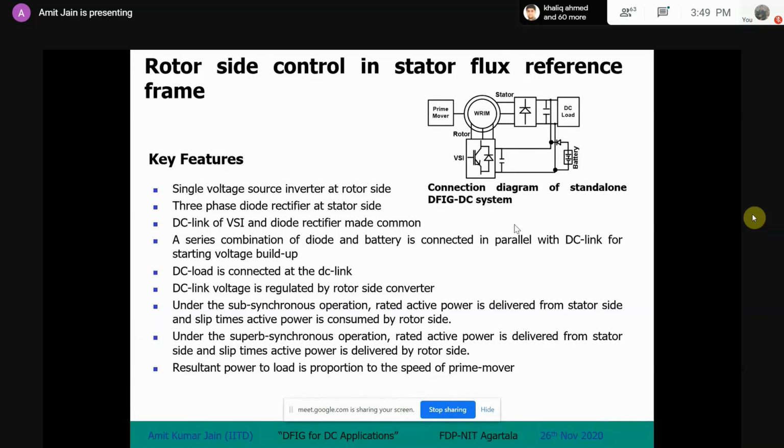It allows very low rating. Can you imagine, only 2 megawatt of power from a 2 megawatt power converter here, whereas with SCIG or PMSG, you need a power converter of 12 megawatt for the same purpose. So this is a highly optimized system. But where is the complexity now? You don't get freebies.